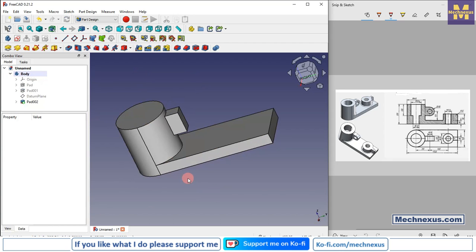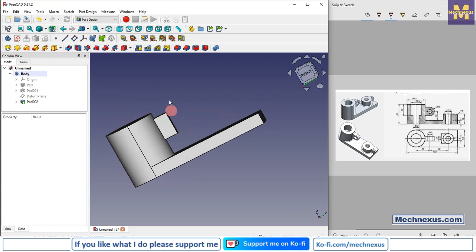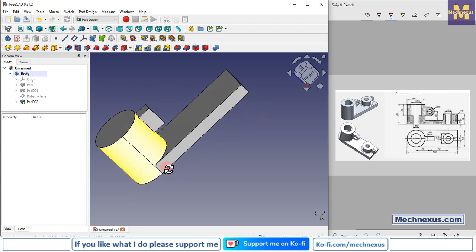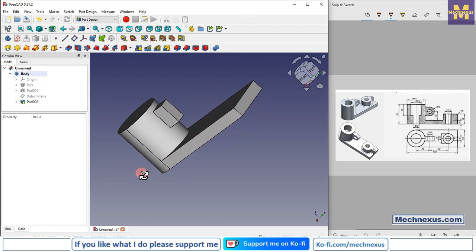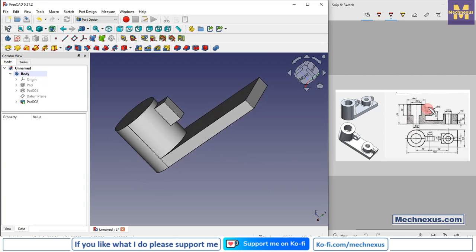So FreeCAD does not support multi-body modeling. If I try to extrude an independent feature which does not have any relation with the existing body, FreeCAD does not allow it. That's why we have given the relation up to face. Now we will provide the fillet, this one.